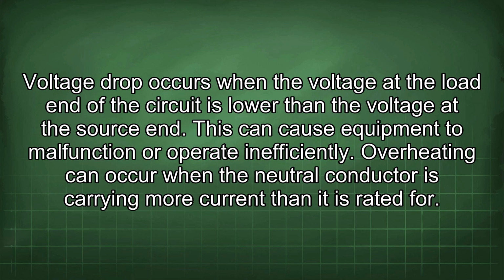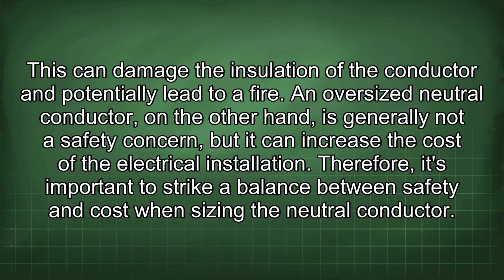Overheating can occur when the neutral conductor is carrying more current than it is rated for. This can damage the insulation of the conductor and potentially lead to a fire. An oversized neutral conductor, on the other hand, is generally not a safety concern, but it can increase the cost of the electrical installation. Therefore, it's important to strike a balance between safety and cost when sizing the neutral conductor.